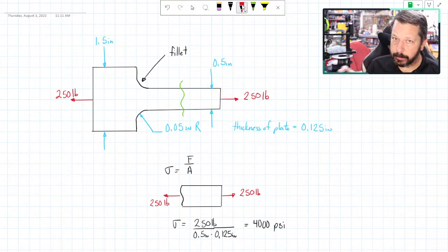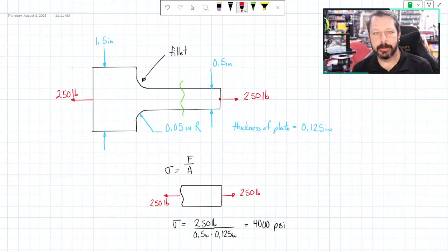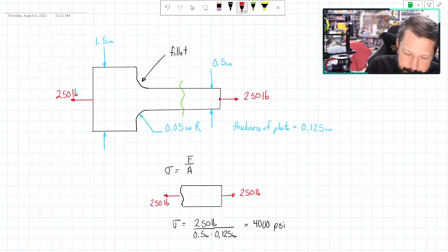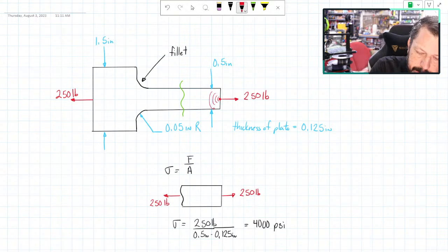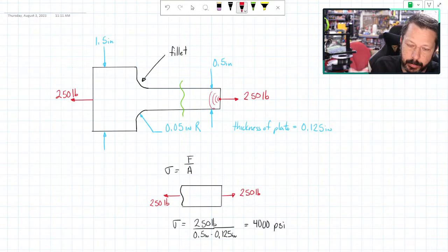well, for one thing, the way that I've shown this picture is I've applied a whole bunch of force at one little point right here. So normally these point loads that we draw, like the single arrows, they're not really realistic. Most everything is spread out over some amount of area, and they're not infinitely small, because that would create a really high stress concentration. So I'm trying to draw here the higher stress at that point load.